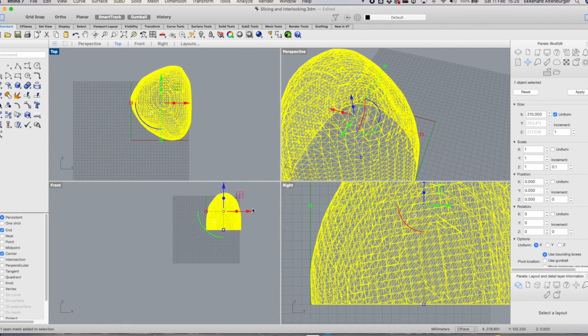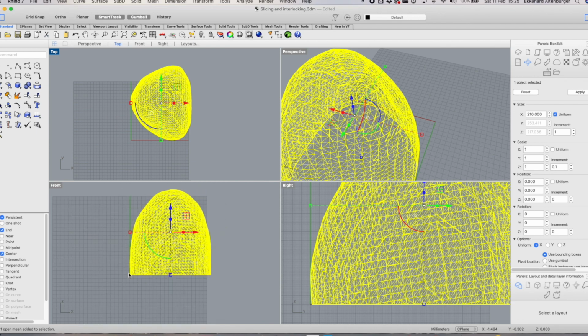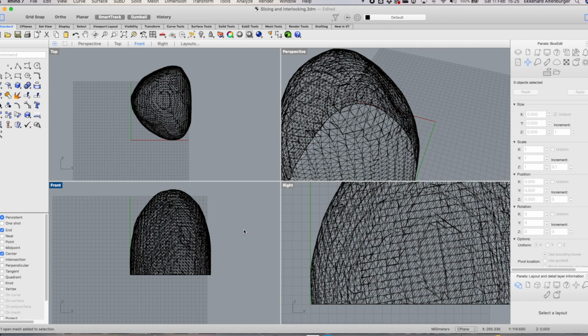The first thing I want to do is slice through it horizontally to create some supporting ribs. And we do this again. I'm working on Rhino for Mac at the moment, and there you should always use a double button mouse.